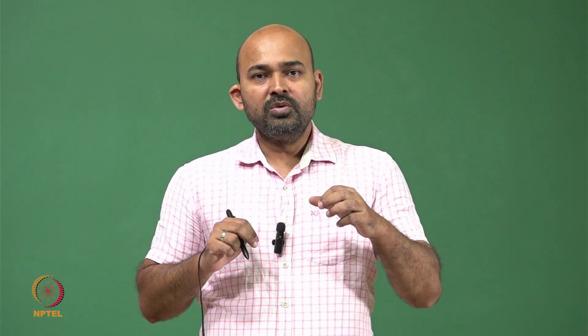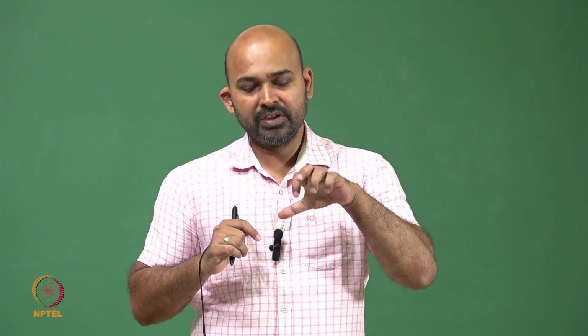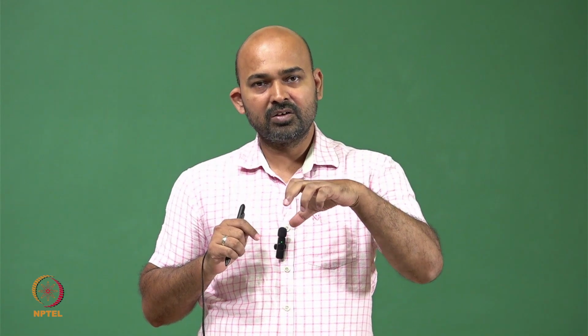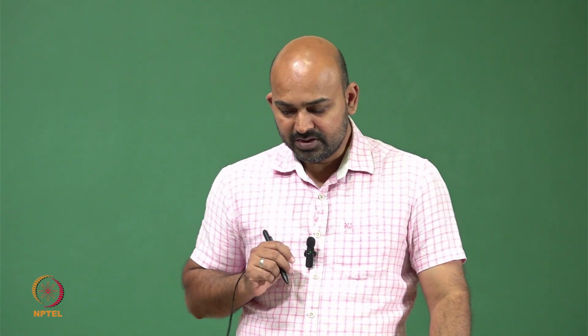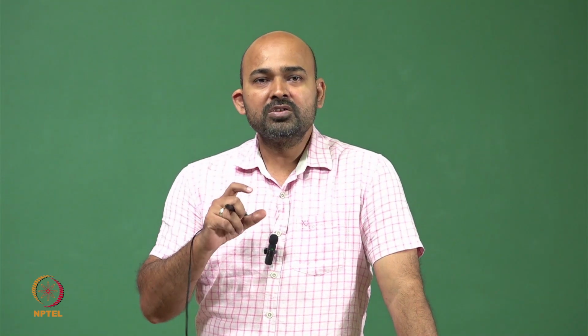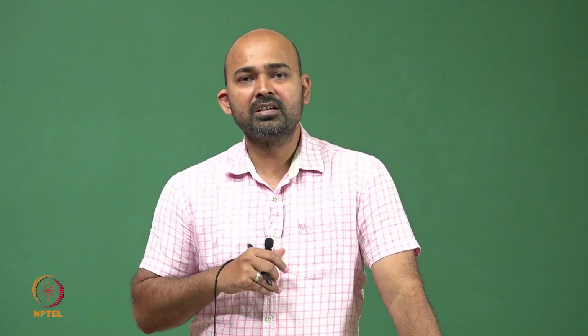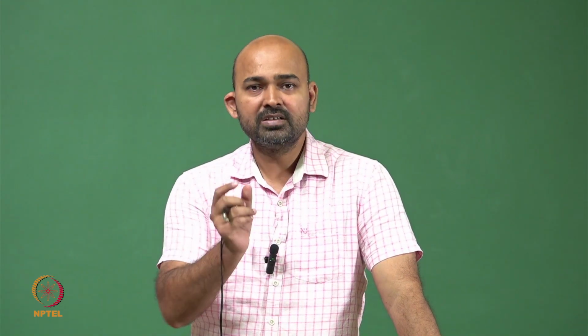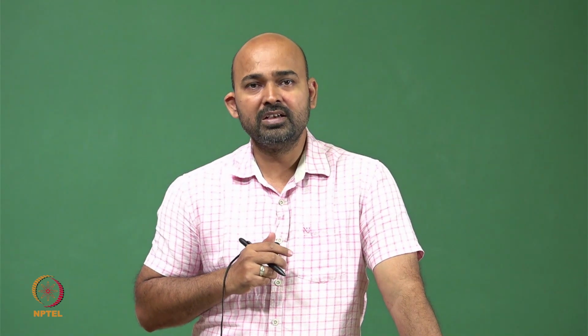This has two electrodes, one from the left, one from the right, and they are interlocked, and we apply the electrical signal on these two electrodes, and accordingly the surface wave will be generated. The performance of the sensor in general can be optimized by adjusting the length, width, and position of this IDT structure.